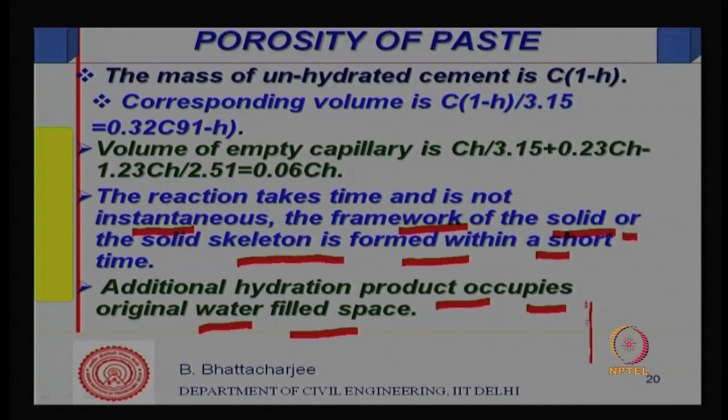The structure is formed very quickly, but some spaces are blank. Those blank spaces are filled in by additional hydration product, because a porous solid structure is formed once it solidifies. Remember the blue colored water which the outer product filled in, leaving some water filled space.